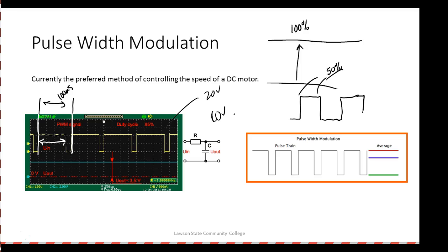So what happens is the slower we run the motor using a resistor or a transistor that we're working in what we call as a resistor, then it's going to get real hot when the motor runs slow, and it's going to cool down when the motor runs fast, y'all understand that. Pulse width modulation, these devices are either what? They're either off or on. So it's like a light switch. So how much power does a light switch produce when it's on?